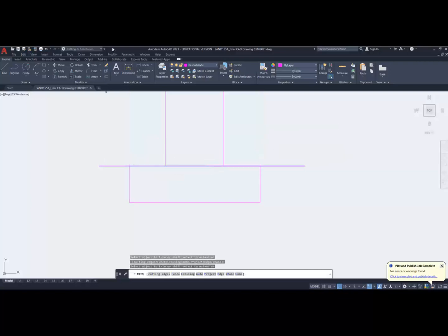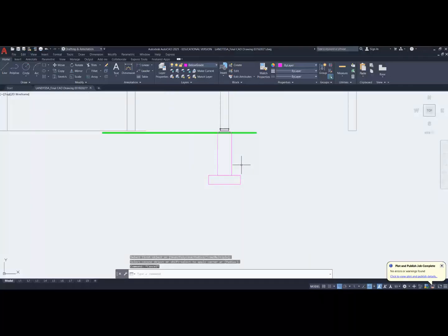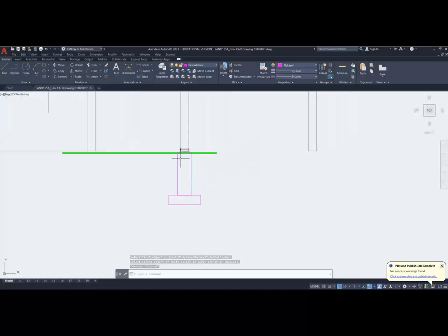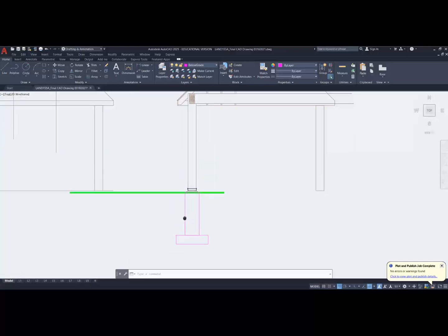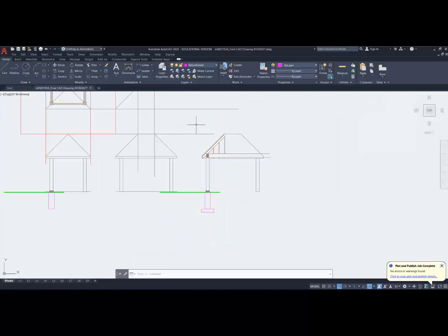There, it's a polyline, so it goes all the way around. And then I can fillet this. So from here, I'm going to take all the details from our first drawing that we did on the pillars for the gate, and I'll use all the notations I have in here. When you've got to this point, the next series will actually identify how to put it in the viewports and make all the notations.